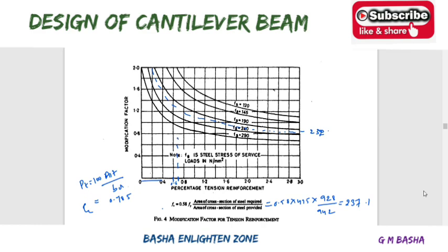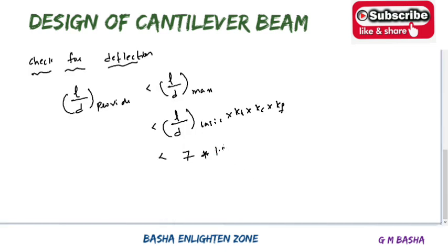So like that I am checking approximately wherever the curve touches, and exactly to that point check with right and left. So how much you are getting? If you are calculating like this, you will get a value around 1.2 or higher. So 1.21, 1.24, 1.22, like that. Somewhere I am taking K_t equal to 1.22. Approximately I am taking some value, which is 1.22. See here, I am writing 1.22.